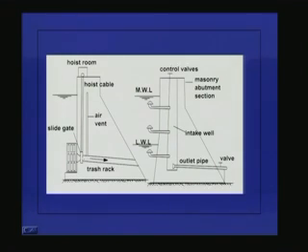The flow into the intake pipe itself can be controlled by a gate, and this is the hoist cable for the gate, and the gate itself can be controlled from the top of the dam. And we also need an air vent here that is meant for expelling air during the maintenance period.